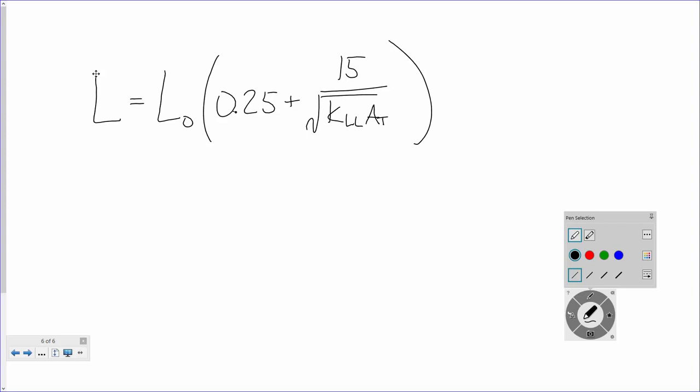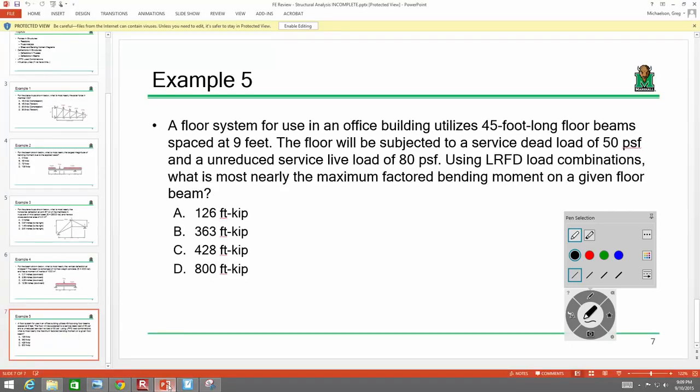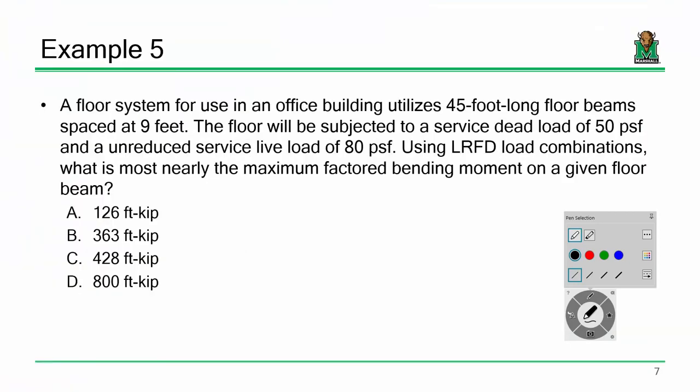Never, okay? So the design codes specify a certain live load, but we are allowed to reduce that based on the probability that we're not going to see all that design load throughout its design life, and that's live load reduction. When you get to concrete design and steel design, you end up using factored loads: 1.2 times the dead plus 1.6 times the live. Well, you have to calculate your dead loads and your live loads in order to use that. So that's what this problem is about. Because it technically is structural analysis. It's not design. Okay? So let's go through the problem.